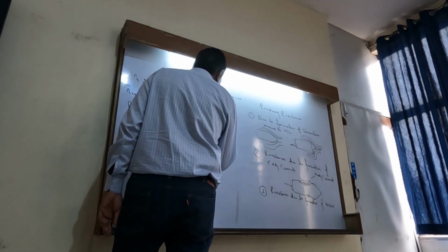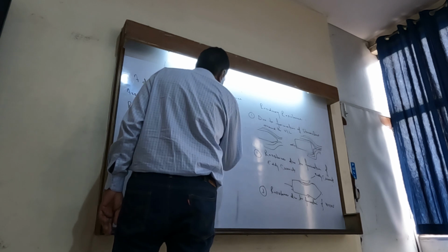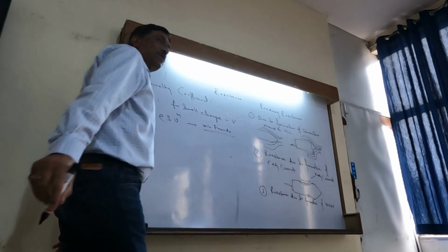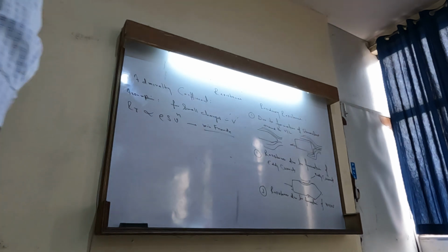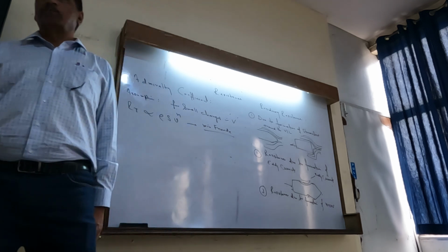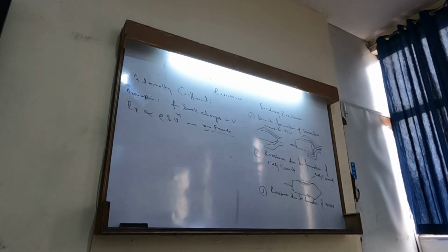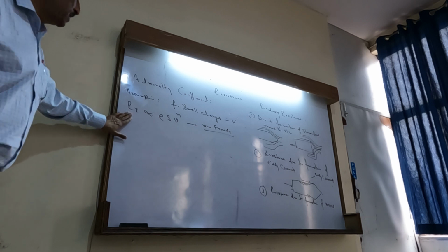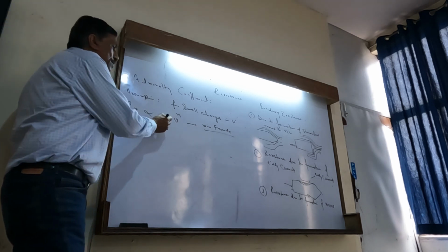Mr. Wayne Froude. You must have used Froude formulas in naval architecture, yes or no? Very awesome. Froude has given us a lot of formulas, just like Newton is so famous. Similarly, in the shipping industry, a lot of formulas have been given on the basis of extensive experiments, and by application it has been found they truly represent the particular parameter. So total resistance can be said to be proportional to rho into S into V.